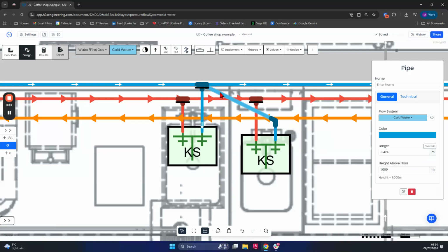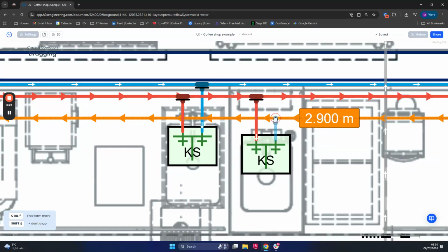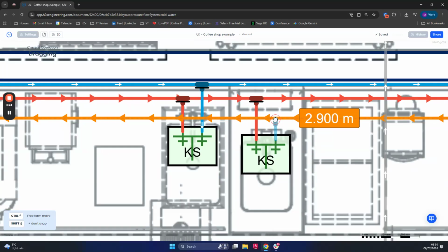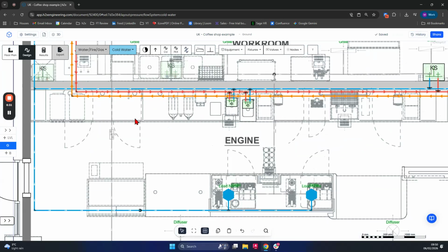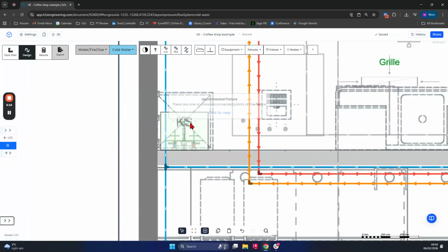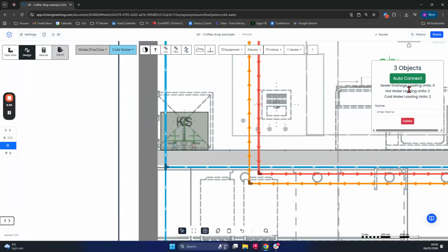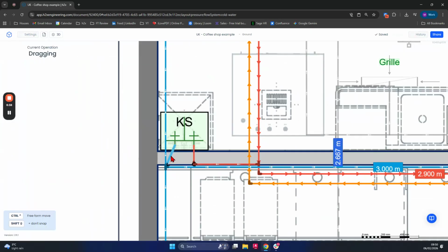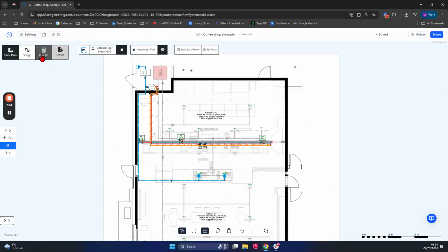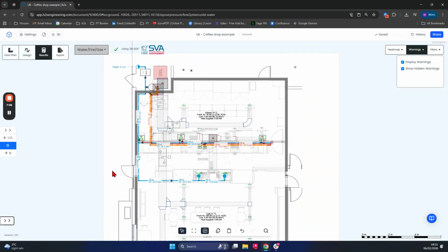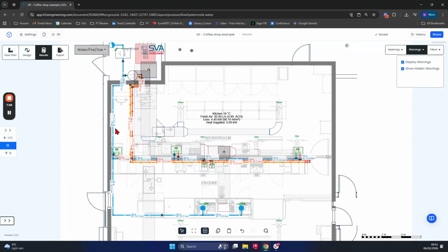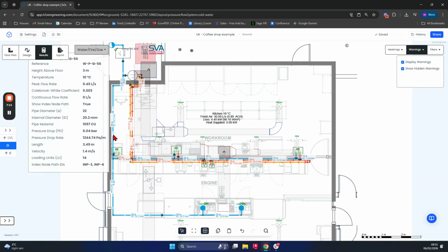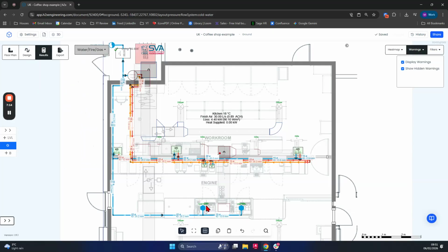You might have a situation like this where the calculated route isn't necessarily what you want. In that case, you can click on this cap end here after deleting that pipe, hover over the connection point over to there. Now we'll just do that one more time for this kitchen sink. Maybe connect that up differently. We hit results. H2X is then going to tell us the required pipe sizes based on the diversified peak flow rate of each of those connected fixtures or the load nodes.